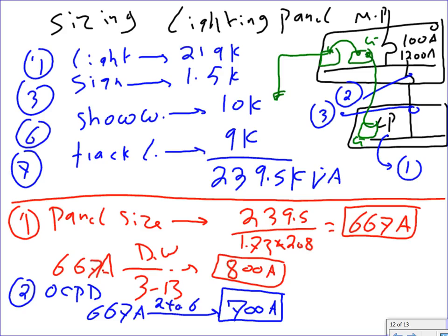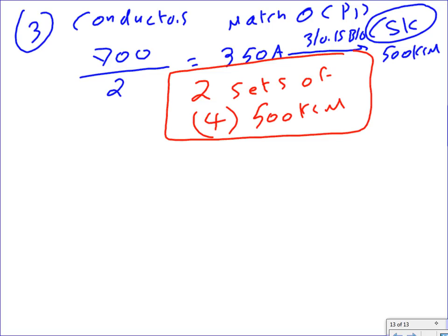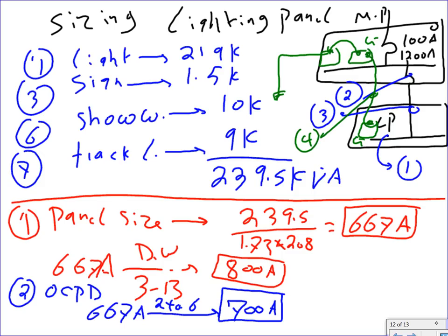See that conductor here? That will be number 4. Everybody see the grounding going from the main into the lighting panel. Done. You size this one, Brad, based on the overcurrent protection device. So my overcurrent protection device is number 3, or should be number 4.